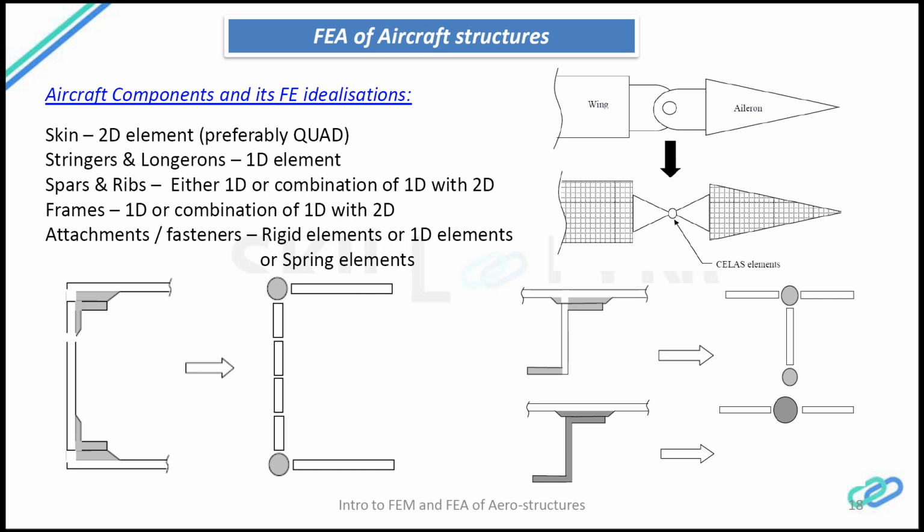In order to understand the internal forces and internal reactions, I need a little bit more accurate model, which is this one. But in terms of the global forces, I just need to understand the loads at the aircraft interfaces, for the whole aircraft. Then my region of interest is not the wing or anything in particular, so I go for this. So moving on to the next slide,